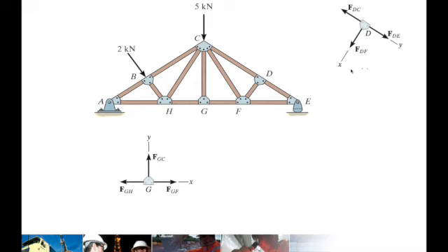Okay, now that we conclude that DF is zero force, if we do a free body diagram of joint F, so if DF is zero force, then F looks like a joint where there are only 3 members and 2 are collinear. So the third one, which happens to be member CF, is a zero force member.